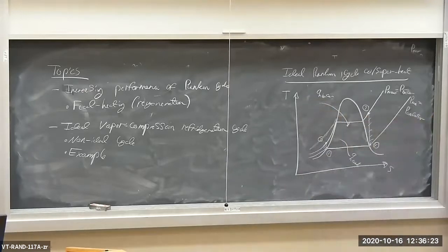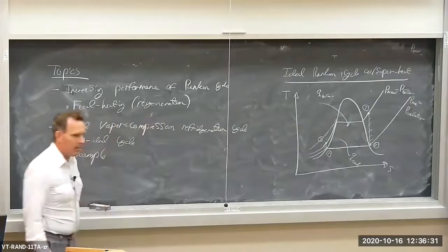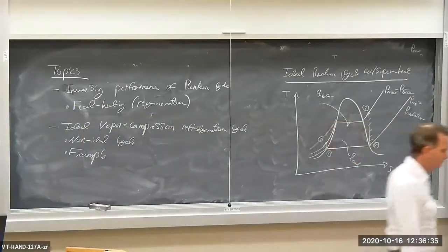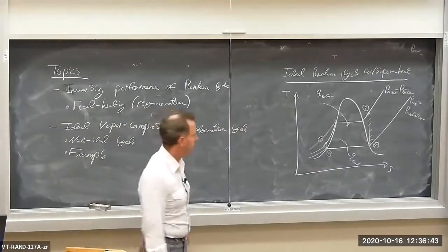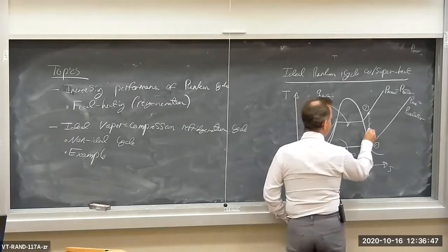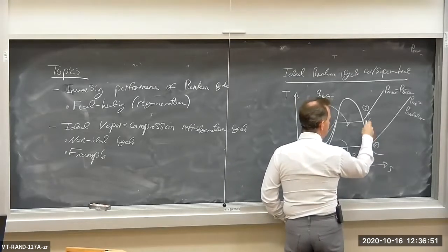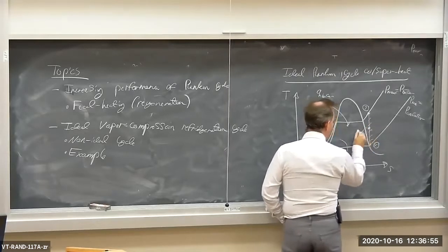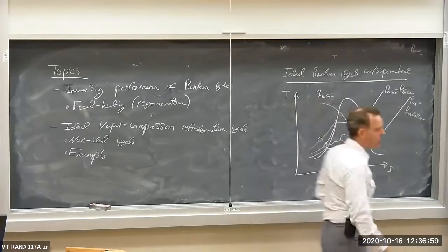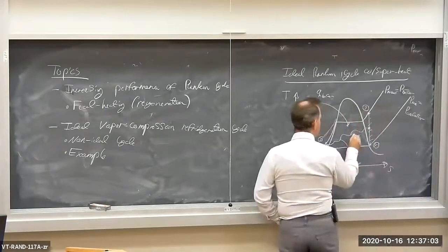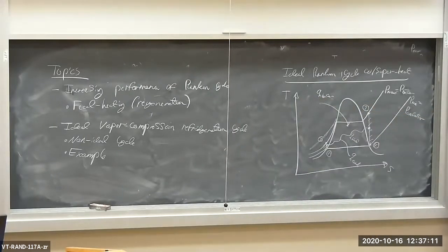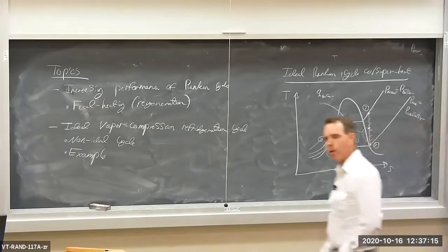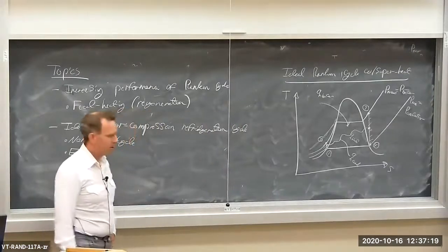Now, if you recall from the Brayton cycle, the idea of regeneration was to take some of the heat that would have been rejected to the atmosphere and take it back and preheat the air before it went into the combustor. The idea is kind of similar here. It's not quite as effective, but it can be somewhat effective. The idea is to take some of the energy or heat, intercept some of the energy in the flow somewhere during the expansion process in the turbine, and feed it back during the compression process. So the idea is to take some heat, Q bleed. Let's bleed away some heat, some energy from the high temperature side and funnel it back to the low temperature side in the hope that we can improve the efficiency of our Rankine cycle. Okay, so that's the idea.